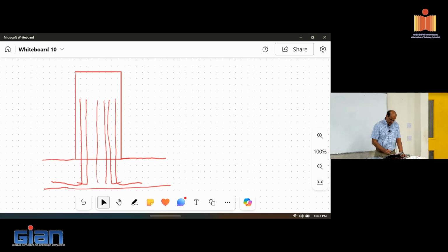One is, if I'm applying load. Gravity load is something that we talked about, I think Satya also covered. When you apply the loads, gravity load is relatively easier to transfer. Connections are not subjected to as much forces, and the details can be very simple. The lateral load is where we have been moving towards: how will they differ in terms of the precast versus the cast in place option.